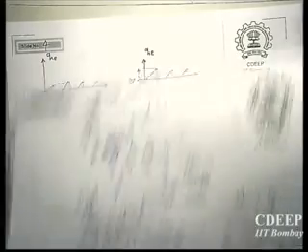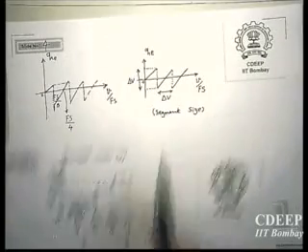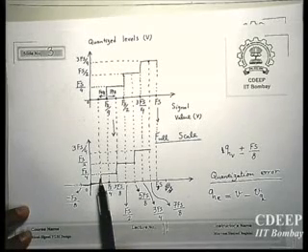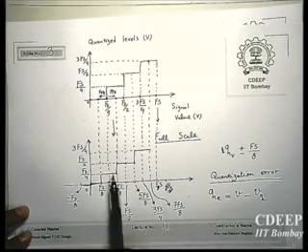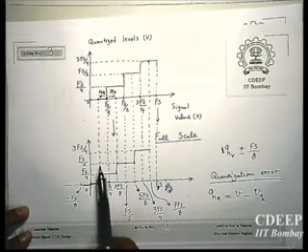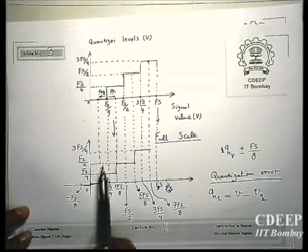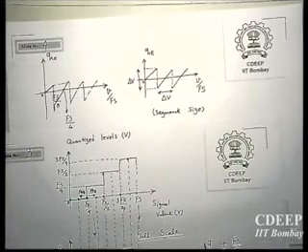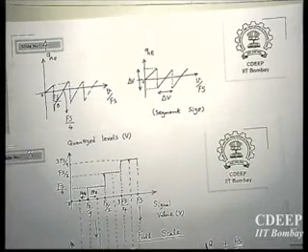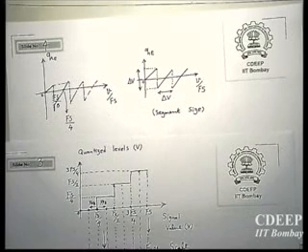And in fact, the spacing of your quantized levels for the signal is delta V. If you notice, the difference between two consecutive quantized levels is here, for example, Fs by 4, which is the same as the segment size, Fs by 4. Just an example. And your error also will be the same as this.